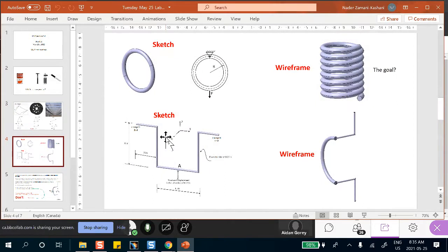One is if your structure, such as this ring, for example, this frame, can be drawn or can fit, let me put it this way, in a sketch, in a two-dimensional plane. Then you can very easily create these sketches and proceed from that point on. You take it into 3D space, of course, that's still a sketch, but it's in two dimensions, in a plane. And then you go from that point on, you join it and mesh it, and so on.